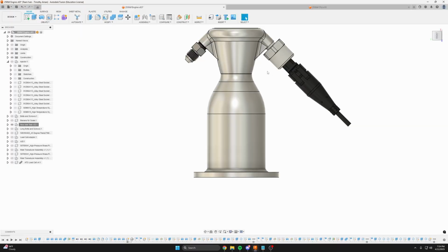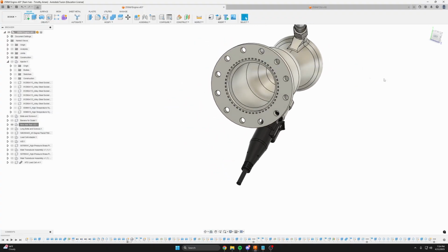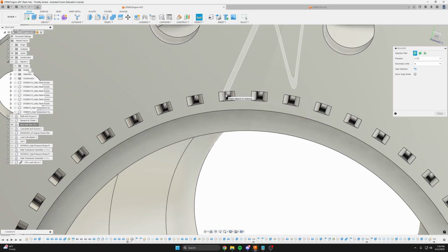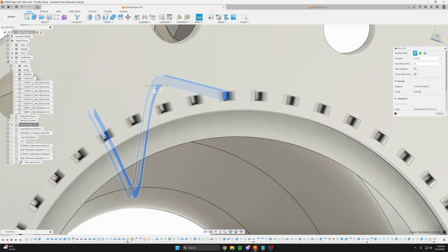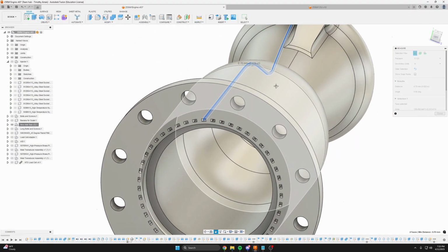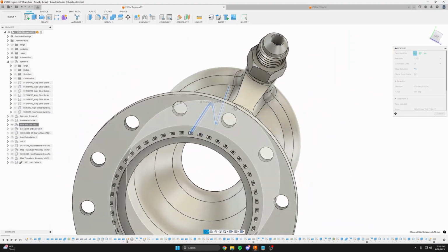They're very small grains of powder, and depowdering them can be kind of a pain. For us, it proved very difficult. On this engine, our cooling channels were 0.7 millimeter wide slot channels, constant area channels down the whole length.